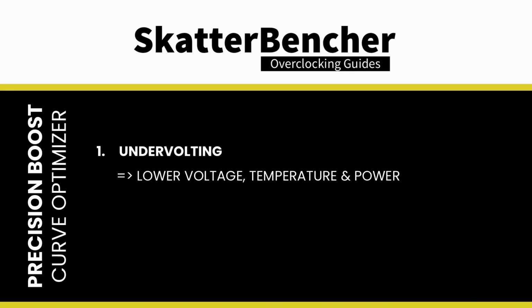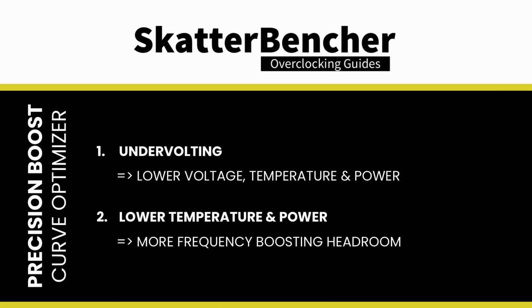And the more you dig into the details, the more you become aware of its intricacies and how it applies to your daily overclock. We use Curve Optimizer most commonly by applying a negative value to undervolt. And that helps in two ways. First, undervolting lowers the operating voltage, temperature, and power consumption. Second, as a consequence, the Precision Boost 2 algorithm can leverage the additional headroom to boost to higher frequencies. So you tend to get lower temperatures and higher performance. It's a win-win.